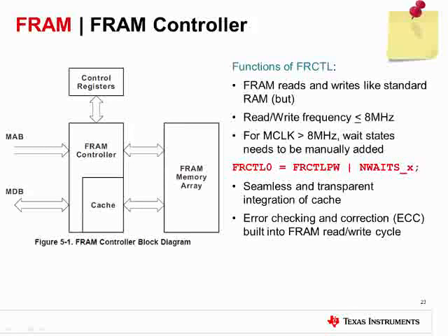In addition, the FRAM has a cache mechanism. This helps to avoid a performance hit from the FRAM accesses. By fetching a few instructions at a time in the cache, anytime you have a cache hit, you won't incur the wait state penalty. We estimate that most typical code averages about a 66 to 75% cache hit ratio. So this means you would only see the wait state penalty 1 in every 4 cycles, which mitigates any penalty in your performance for wait states.